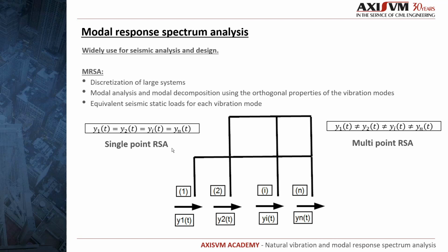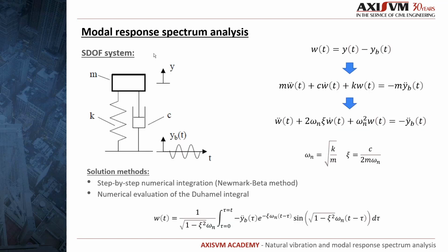For simplicity, we will present here only the single-point response spectrum analysis. We will assume again an MDOF system. Considering base excitation and introducing the relative displacement, the equation of motion can be rewritten like this. Dividing by the mass m, we obtain this final form.